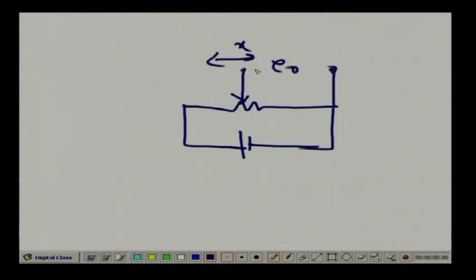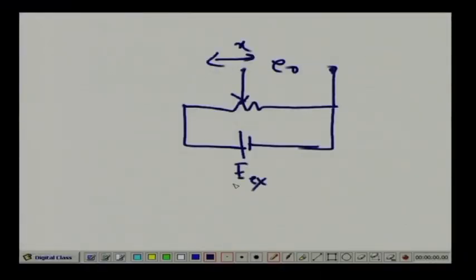Now, you see that the resolution of this potentiometer, that means the output voltage, can be made better and better if I increase the supply voltage value. This is very simple, I just increase the supply voltage E x, the excitation voltage, and the measurement resolution will increase, right. Whereas, in the case of the passive instrument, it is not very easy.